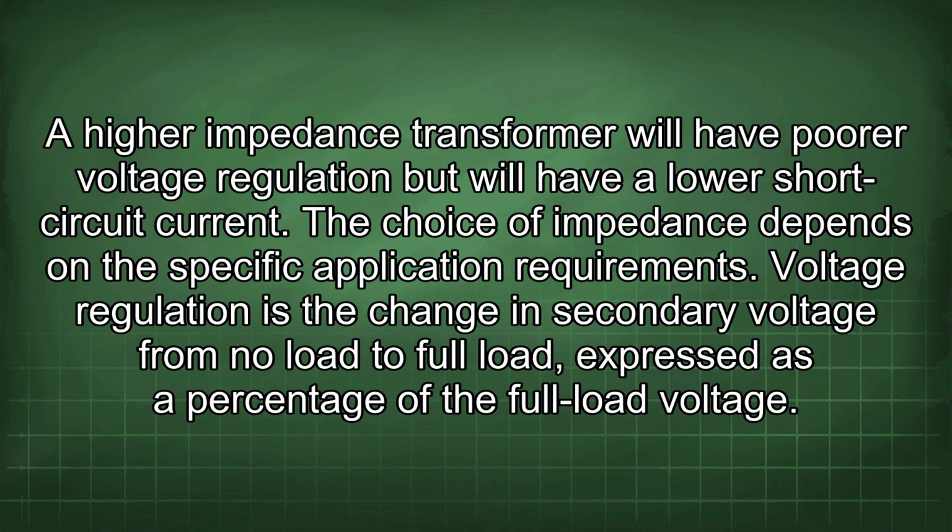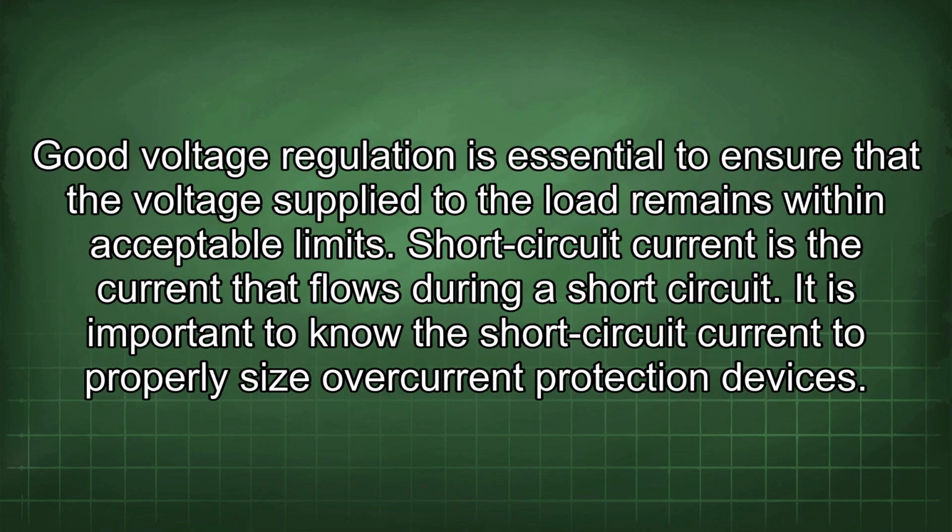Voltage regulation is the change in secondary voltage from no load to full load, expressed as a percentage of the full load voltage. Good voltage regulation is essential to ensure that the voltage supplied to the load remains within acceptable limits. Short-circuit current is the current that flows during a short circuit. It is important to know the short-circuit current to properly size overcurrent protection devices.